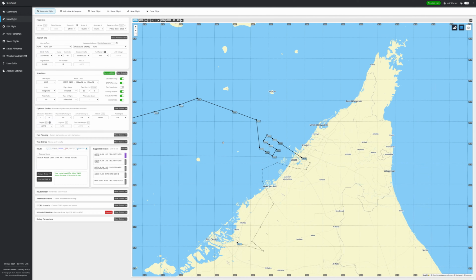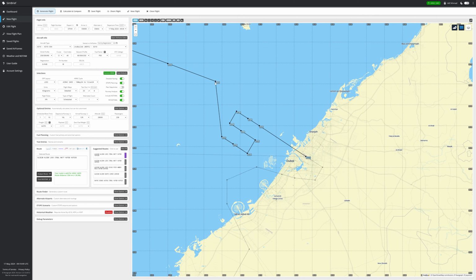Similarly, when the plane is arriving at an airport, it doesn't simply come and land. As you can see, this should have been a straight line, and the plane should have landed at 12 right. But there is a certain path that's coming. This is actually a part of the STAR, which is Standard Terminal Arrival, and it determines the arrival procedure. Also, it contains the speed and the altitude constraints. As I do the flight, you will see it in this video.